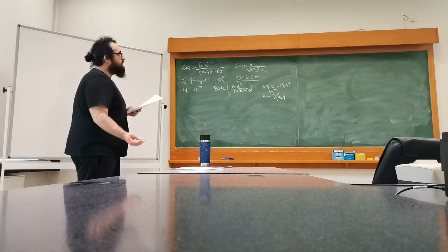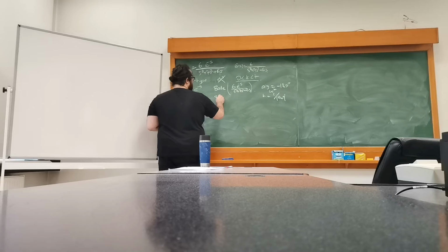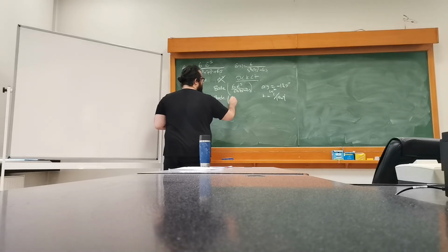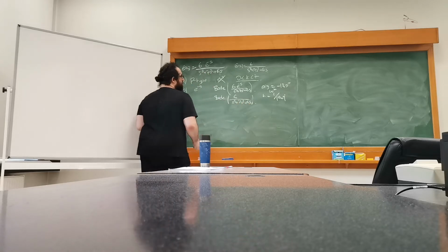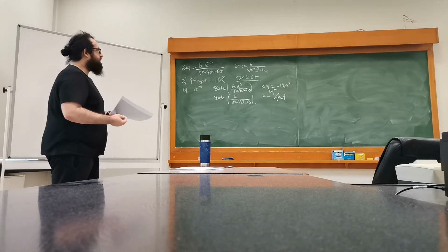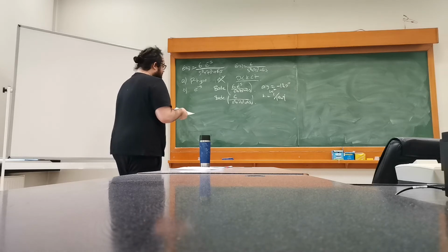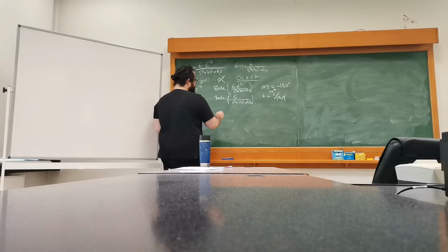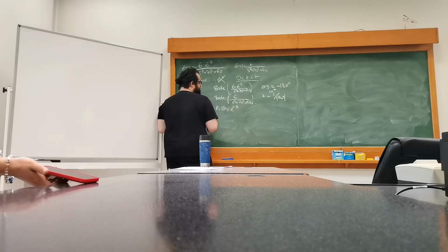But what if we don't have this delay part, but we have the Bode plot of 6 over s cubed plus 7s squared plus 6s? What then? Can we use this Bode plot in order to come up with a controller for the actual system that has the delay? Well, obviously we can, because we have k times G(s) times e to the power of minus s.